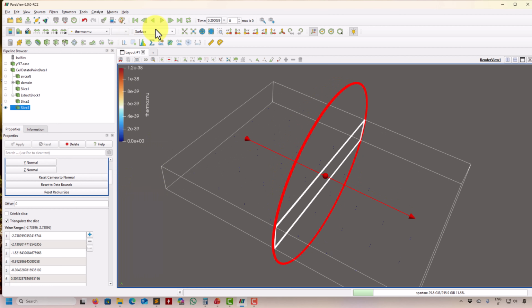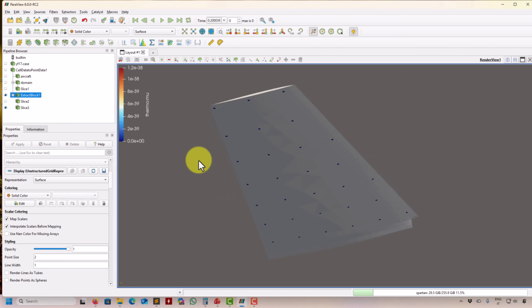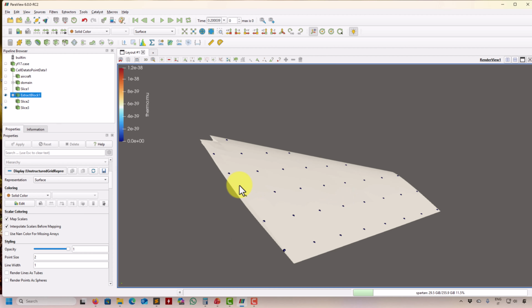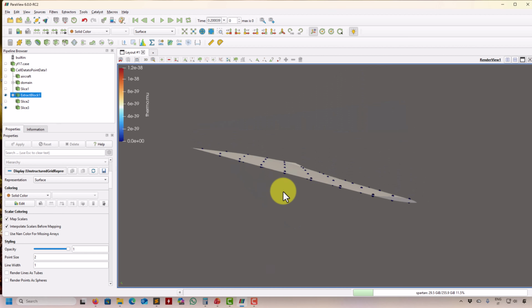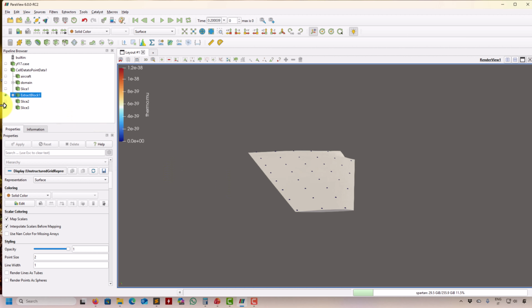So now see that we have points, and these points perfectly distributed in the wing. You can do sampling in these points on the wing. So look at that. By applying filters on filters, now you can get some other geometrical structures that can be helpful. Okay, and as I say here, for instance, you can say, okay, release streamlines from these points. We have seen a lot of streamlines, and that's it. Or plot, or show me the pressure here, or whatever you want. Okay.